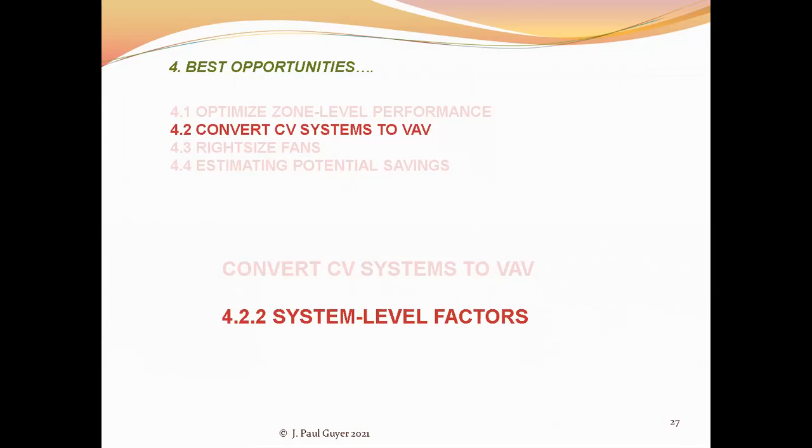And you need to check the equipment accessibility of dual duct systems where the zone dampers are located out in the conditioned space. Is the ceiling a T-bar system that facilitates access for equipment installed above the ceiling, or is it a hard lid type of a system that makes it more challenging to access dampers? And then, of course, with older buildings, there can be asbestos issues that would have to be addressed during any construction work.